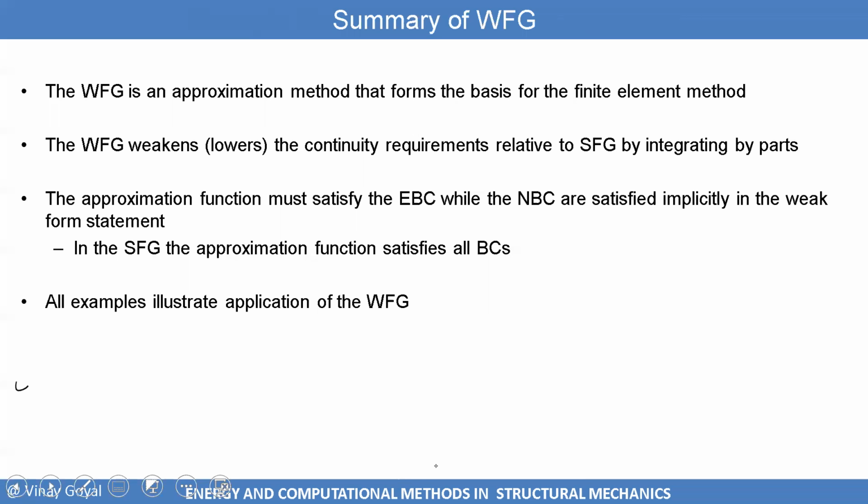We've covered approximation theory in extensive detail. Again, I started with the Rayleigh-Ritz, where you need a functional, and it turns out with structural mechanics problems, a lot of them, you can construct a functional fairly simply. And then if you don't have a functional, you can start from the differential equation, or partial differential equation, start with the strong form Galerkin, which has a higher bar, a higher expectation, so it makes it harder to use for approximating solutions.